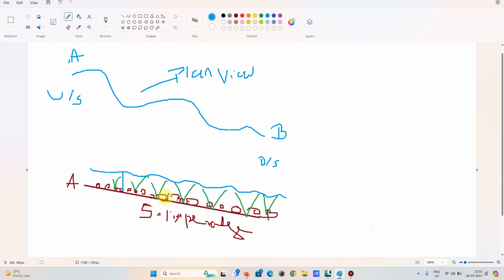So velocity is a function of the slope and the bed material character, which can be incorporated in the model as the Manning's roughness coefficient. I can write it here.